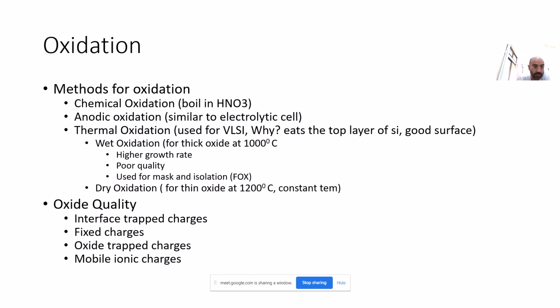For this also there are various methods, such as the fringing method, but usually what is used is the capacitance voltage measurement method to find the layer thickness. This is also used for the measurement of the charge present. If the number of charges is more, then obviously the capacitance will get affected. So the capacitance voltage measurement method we use basically to characterize the oxide layer.